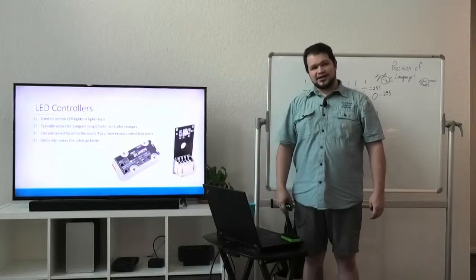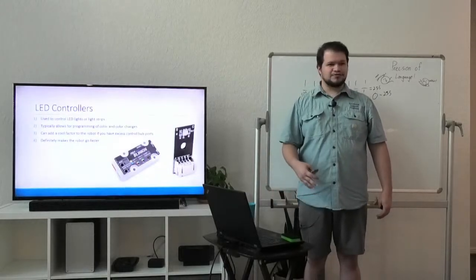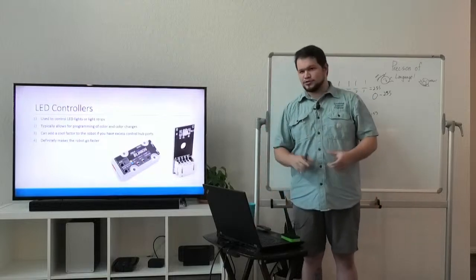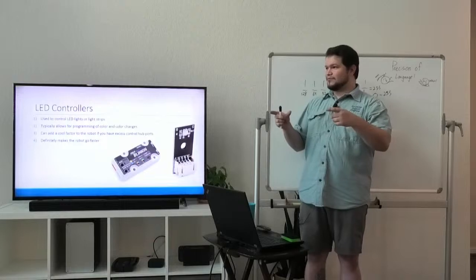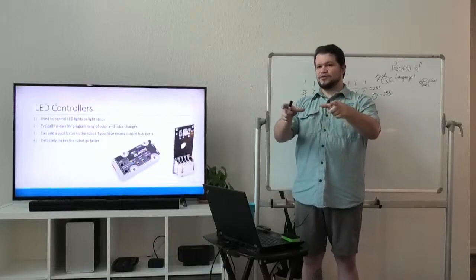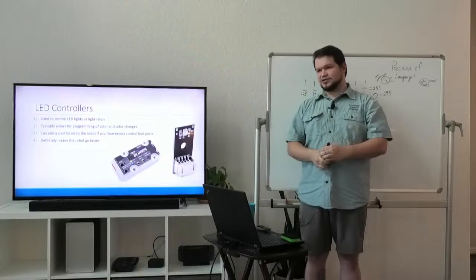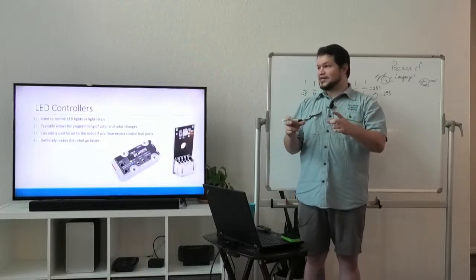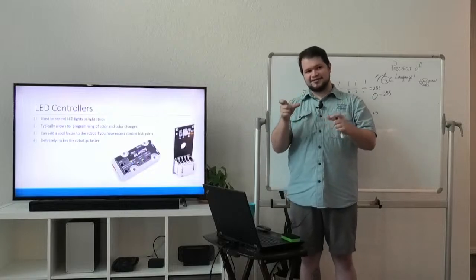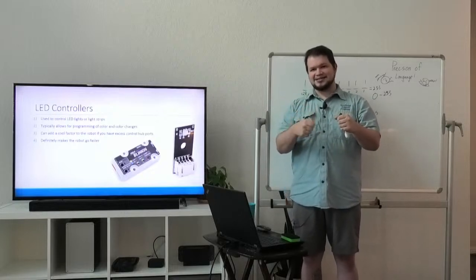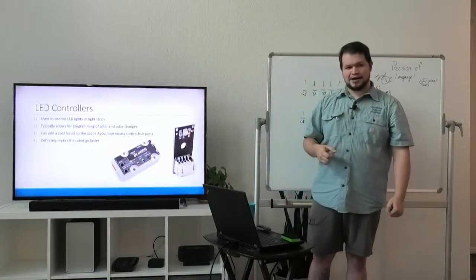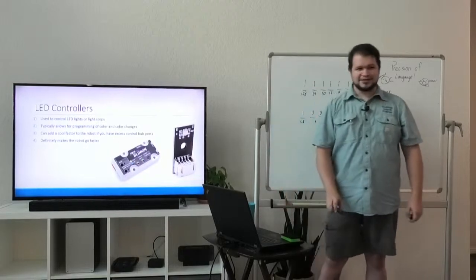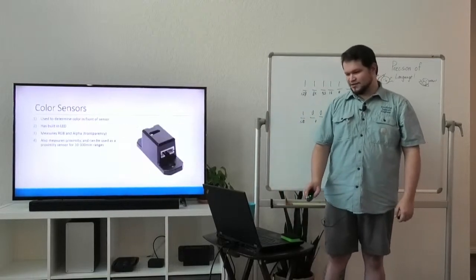In a practical case, LEDs are very useful for relaying information to your driver. So in last year's game, you had to pick up pixels. A lot of times you picked them up from the wing with the robot facing away from you. So if you had an LED on the backside facing the driver, you didn't have to rely on an operator or a person there, human player, to tell you that you grabbed them, because you can have an LED there on the backside that gives you a light as soon as you've actually grabbed the part, if you give it sensors to know that it's grabbed the part. So there are practical cases of using an LED.